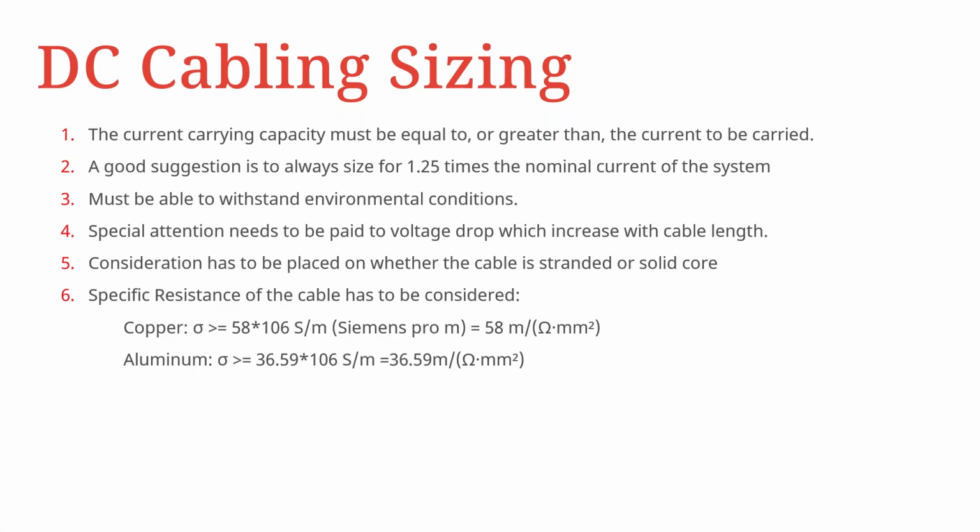The cable must be able to withstand harsh environmental conditions. Special attention needs to be paid to the voltage drop, because this increases with the cable length. And also to be considered is the construction of the cables, whether it's going to be stranded or solid core. But it's good to note here that stranded cables have more current carrying capacity than solid core cables.